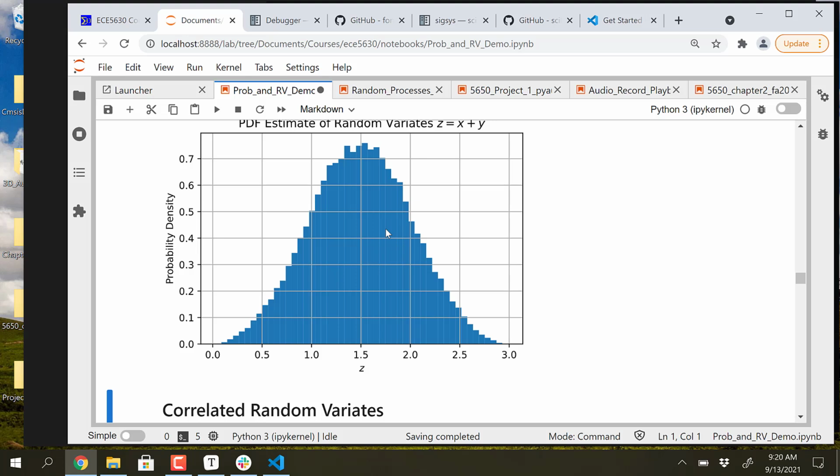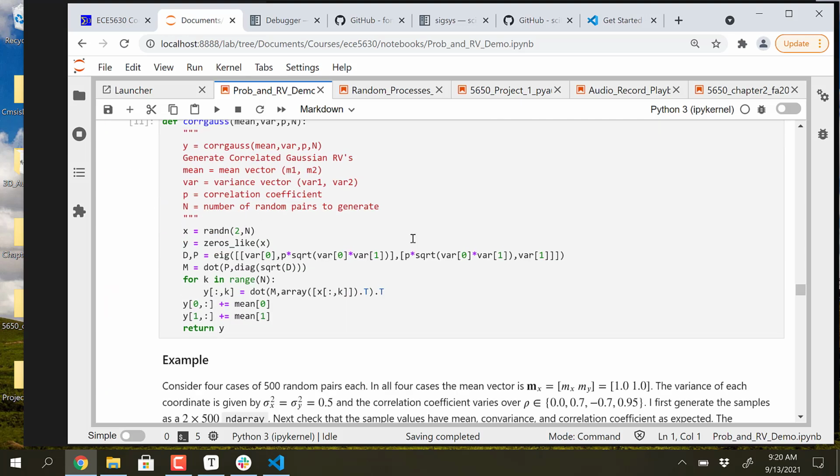So just from the convolution properties, you know that when you convolve 2 finite length sequences, the duration will be the sum of the durations, and the starting point will be the sum of the starting points, and the ending point will be the sum of the ending points. That's just a convolution property. Now it's becoming parabolic because we've got 3 uniforms, and then this eventually looks more like a Gaussian PDF. This looks sort of like a bell right now, but it's not truly a bell. You can calculate crest factor and all those fun things to see how Gaussian it is. Yeah, or other moments and things of that sort. Okay, so we'll be back at looking at this later.